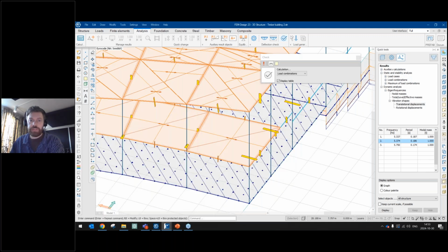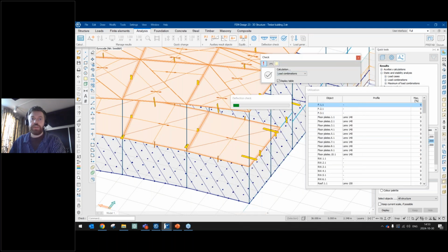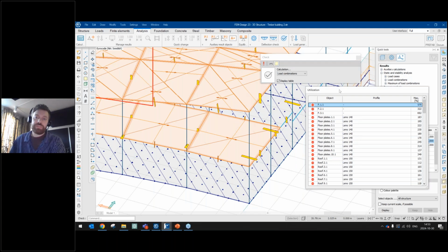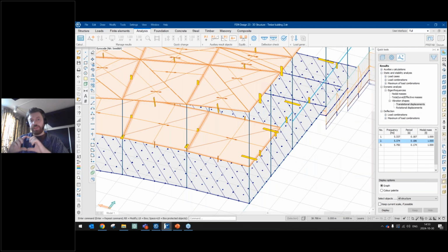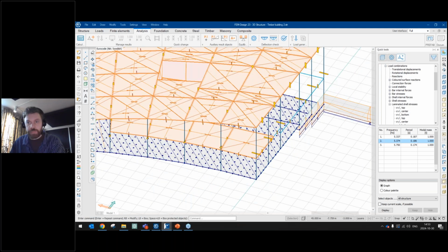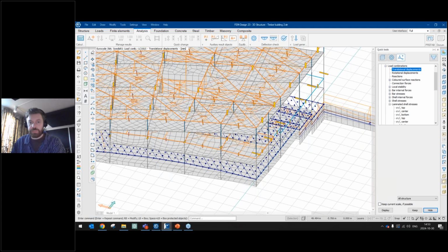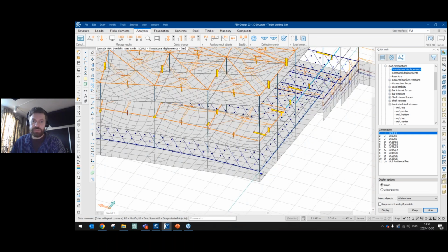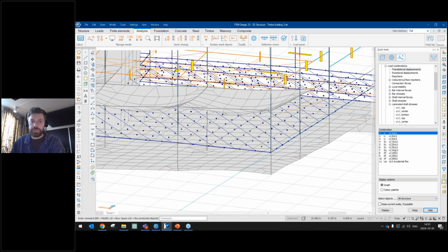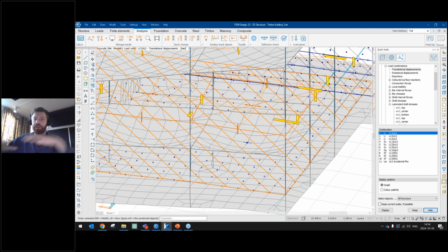So let's just run the check real quick here. If I have a global deflection which is big, the relative deflection will take into consideration and subtract the deflection at the edges, basically. In this case, I have calculated the bedding modulus, and the deflection in the bottom bedding modulus is quite large. If I take a look at the global deflection, I have some global deflection at the bottom here, which will influence, of course, this deflection over here. If I take a look at the specific value in the middle here, it's actually also including that the entire house has sunk down a couple of millimeters.